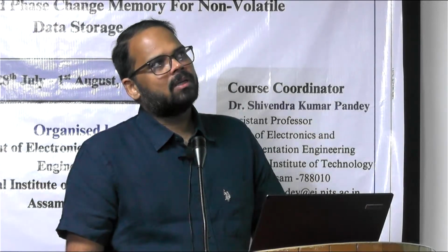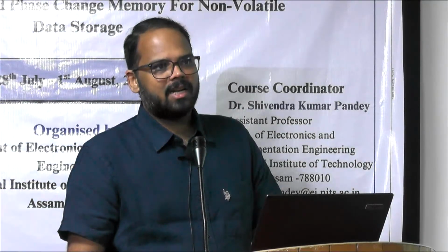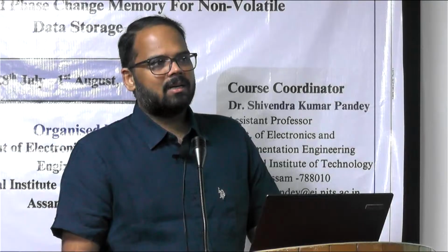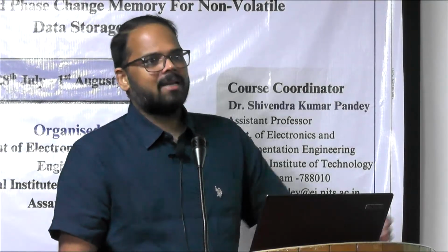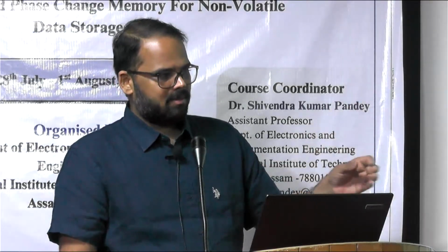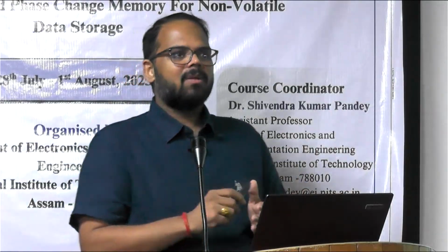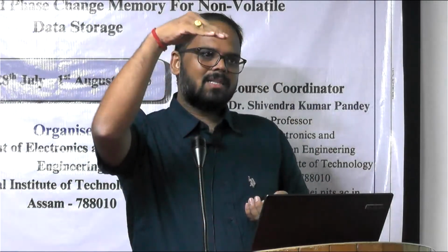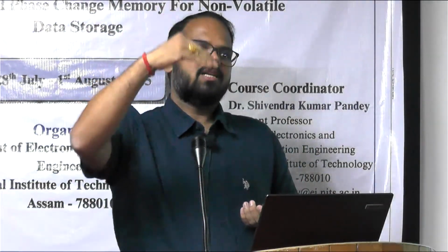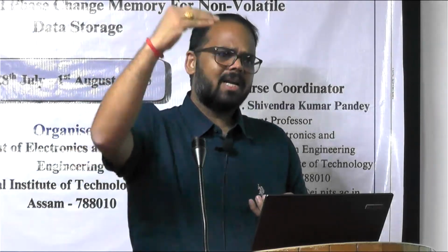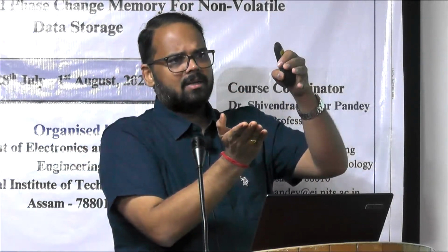Yes, for endurance you should have a proper programming technique. After applying the depress and potentiation electrical pulses, you need to read the state of the PCM device for a particular time, say 1 hour, 2 hours, 3 hours. You need to test whether those conductance states stay constant, or what the variation in between is. Maybe you will get some noise, but there is an error bar. Understood?